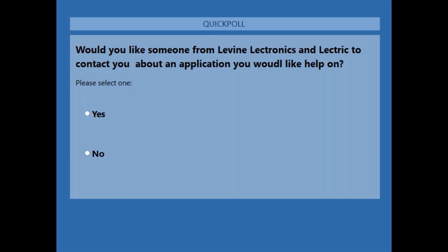Just in the future, if you lose the audio, I suggest you just dial in, because there's no ground conductor in RS-485. I've noticed, yeah, they don't ground the conductors. They do ground the shield. And you only want to ground the shield at one end on RS-485.